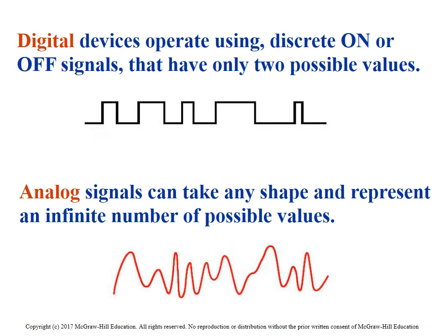Connecting with analog devices, I'm just going to make you aware, analog signals are out there. They don't consist of on or off. They're variances between 0 and 10, or minus 10 and plus 10, just some range of values, so it's not an on and off state. And we do have input and output cards that read that range. Those are analog input and analog output cards, by the way.